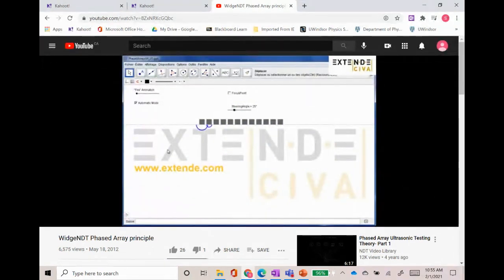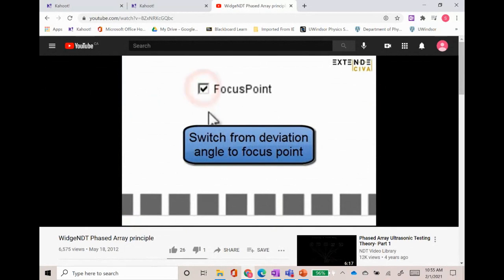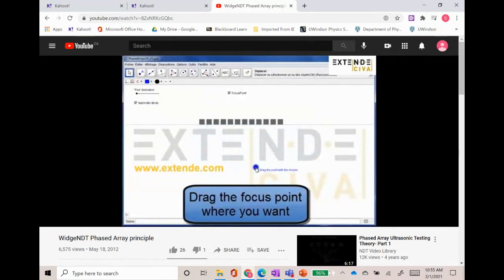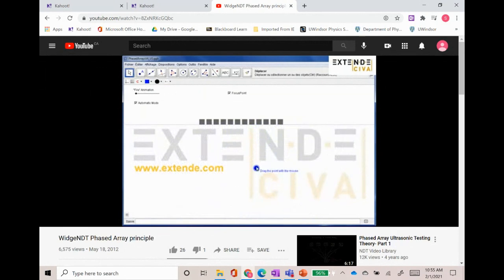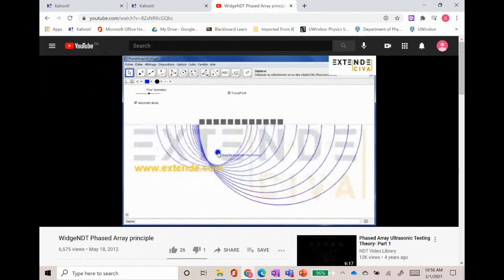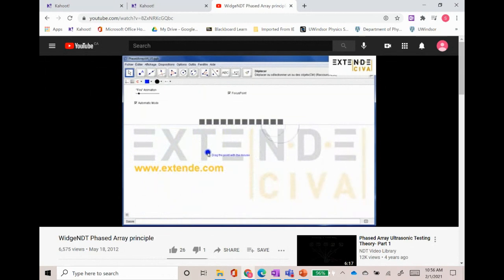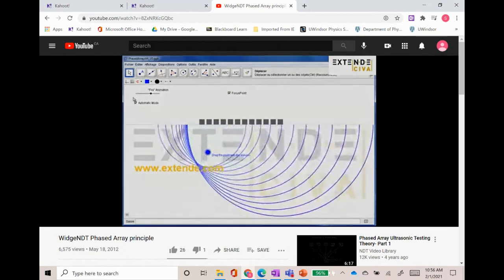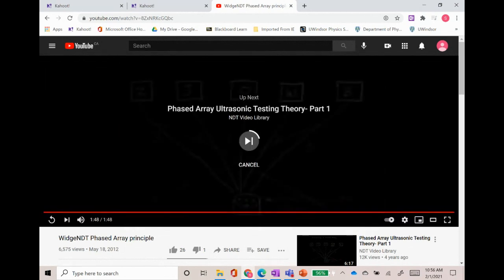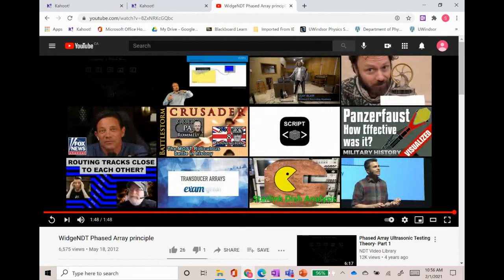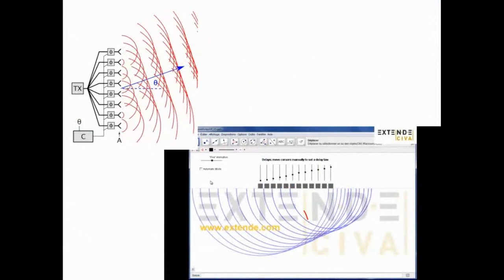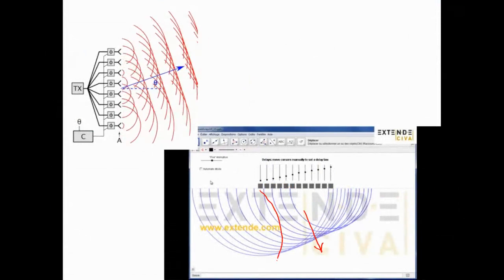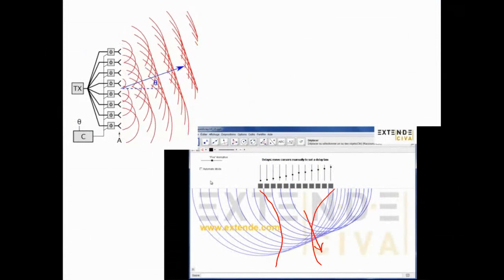Now she's actually going to focus the beam, and this is what's cool. Instead of just sweeping it from left to right, she's going to focus it by having the ones on the outer edges fire at the same time, and then it works its way in, and watch what happens, right? You can make that beam focus at any place that you want. The ones on the outside fire first, and then they work their way in. So just by controlling that phase, you're able to recreate such an image and make something either go out, or focus in like that, or whatever. And that's a phased array.